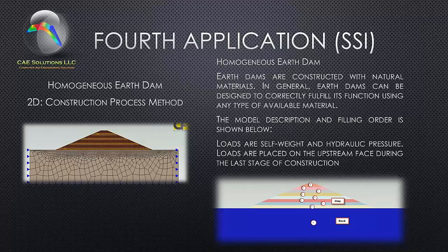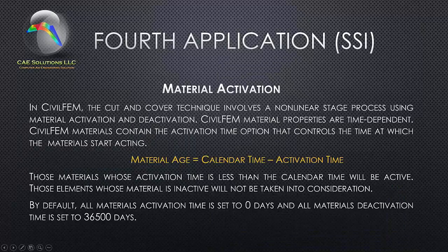Loads are placed on the upstream face during the last stage of construction. The material activation means the fields can be active or inactive. In CivilFEM, the cut and cover technique involves a non-linear stage process using material activation and deactivation. This is similar to gap elements that can be active or inactive when they're touching or not. Again, this is a material activation, in which CivilFEM material properties are time-dependent.